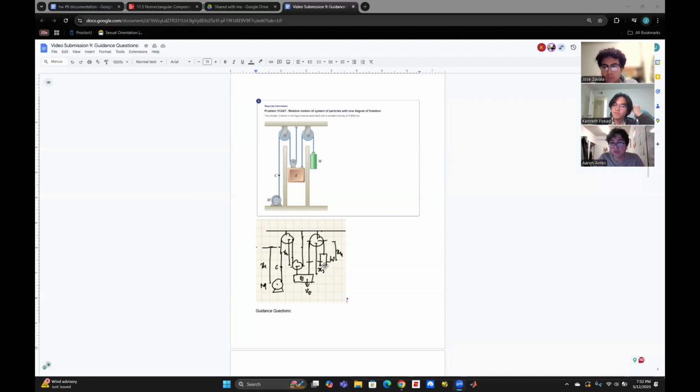Therefore, you know that the velocity exchange is also 1 to 1, which means that E and W move at the same velocity. And there's a ratio for the other pulley of 2 to 1, which means that if you input a force on VT, then it will do double the force on E. But work is the same, which means that it has to do double the displacement.